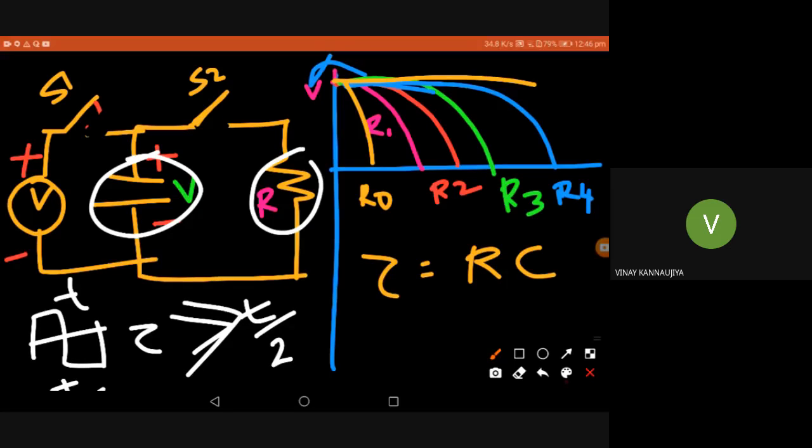Another question is whether charging and discharging are both very fast. No, discharging is not fast. Charging is fast. Why? Because in the charging circuit there is no resistance. When the capacitor is charged through the clamper circuit, there is no resistance in its path. So charging is instant and discharging is not instant. Discharging is very slow. That is up to the designer.